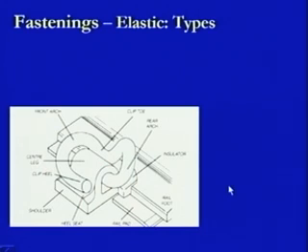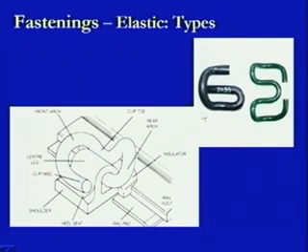This is another diagram where we can see the different types of clips which are being used. Here it is coming this way, and then it also puts a pressure on 2 locations, here as well as here at these 2 locations. This is the foot of the rail section, and here we are using the insulator, and this rail section is also using a rail pad. So, this is a rail pad being shown at this level. So, this is one type of clip which is used.